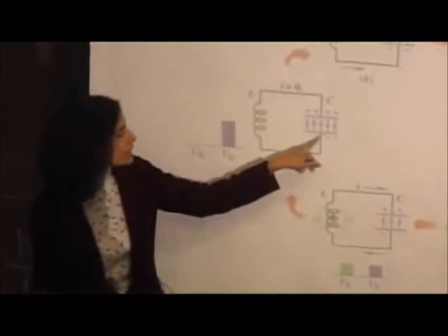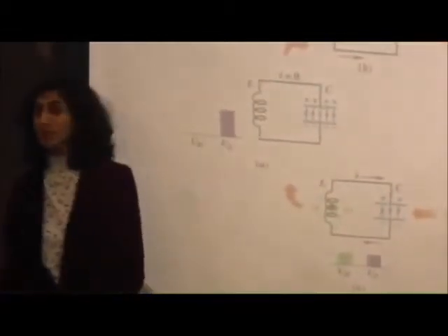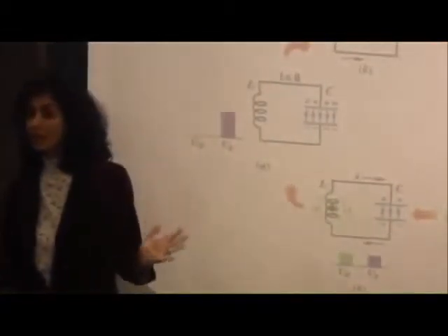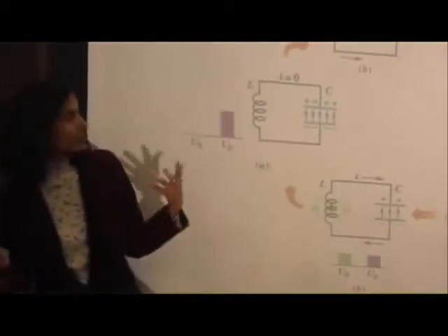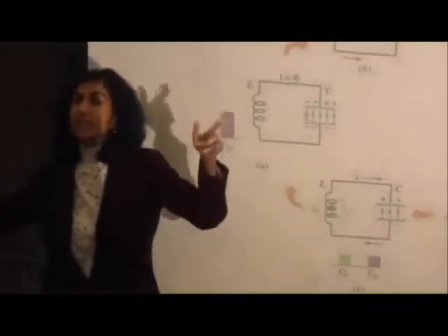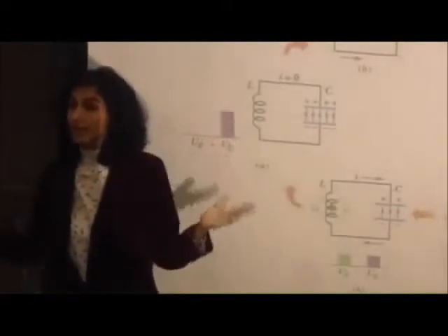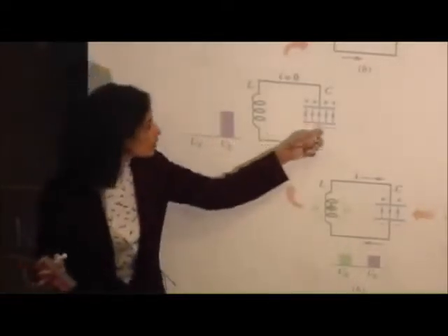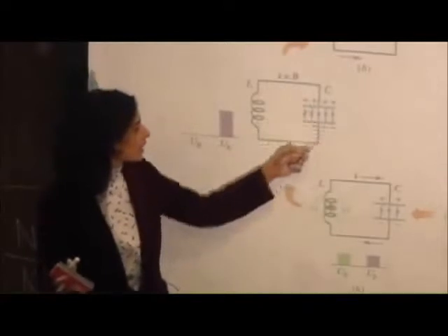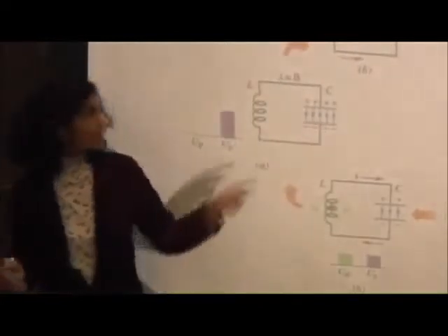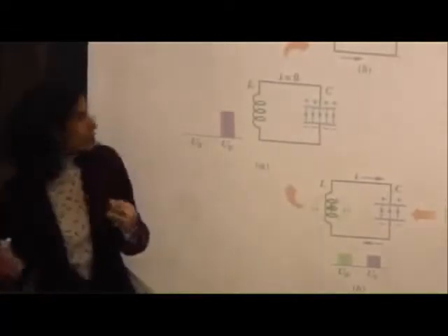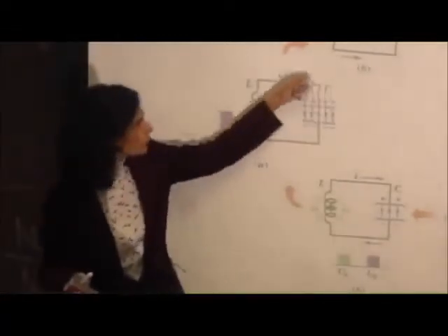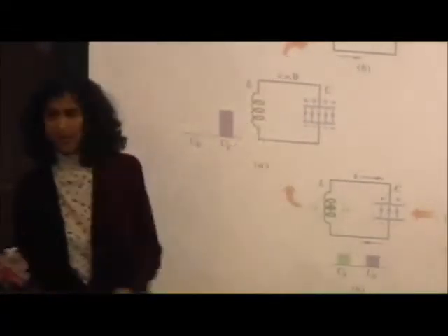So basically what's happening is these electrons are going and combining with the positive charges, and that is what's giving rise to the current. That's what we say. And we use the language, we say the capacitor is discharging and giving out this current, because do you see that the charge in the capacitor will decrease as the negative charges go and combine with the positive charges, and you see a current flowing, right? So starting from zero current, you will start seeing a current in this direction.